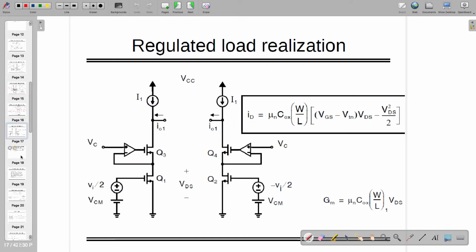You can separately do the same thing, because look, you have kept one diode or one transistor which is actually tunable. So instead of that, you are keeping two things on top of it, on top of actually two inputs, right? So when you are doing this, your current is nothing but mu Cox W by L, and this is the one if this is in triode, right?